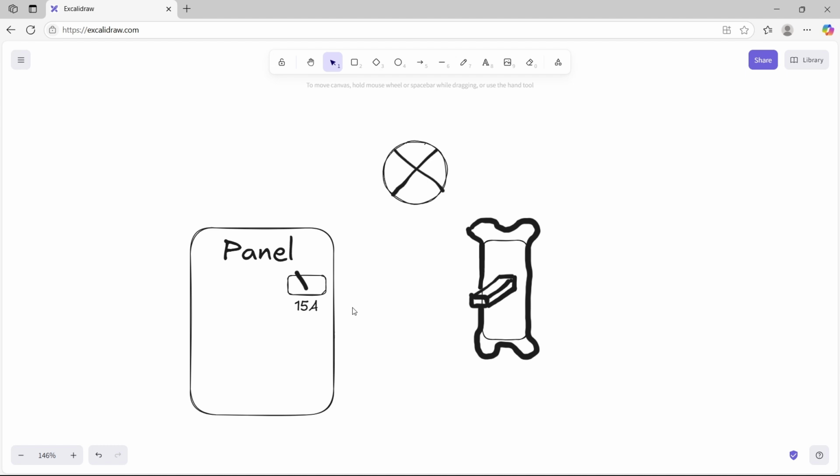And then the moment that it exceeds, in this case, 15 amps for a prolonged period of time, for 5 seconds or 3 seconds or whatever it's rated for, the circuit breaker will trip, it will open the circuit, and it will not allow current to flow. Then you have to go reset the breaker and flip it back on, and then you can resume normal operation.